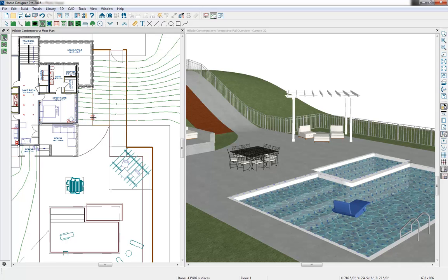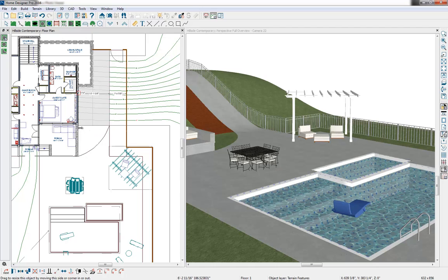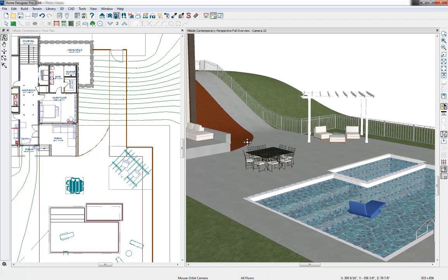Use our break line tool to reconfigure the shape of that. So we'll break it right in that intersection and then bring it over. And then I can single click and drag that corner down, select this edge and make that an arc so we can match that up with the arc of our kind of pathway there. So very quick and easy to drop in a whole garden bed area within that space.